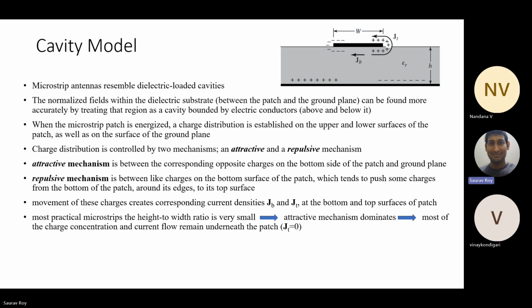That is why it is immensely important. From this equation you can analytically calculate the radiation pattern of this microstrip antenna through equations, not through any measurement or simulation. It almost matches the simulated or measured pattern. That's why this cavity model is almost exact.